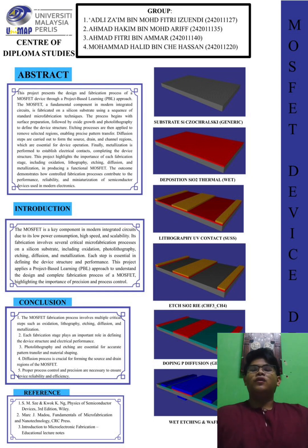The next one, we are going through the introduction. MOSFET is a key component in the modern integrated circuit due to its low power consumption, high speed, and scalability. Its fabrication involves several critical microfabrication processes on a silicon substrate, including oxidation, photolithography, etching, diffusion, and metallization.